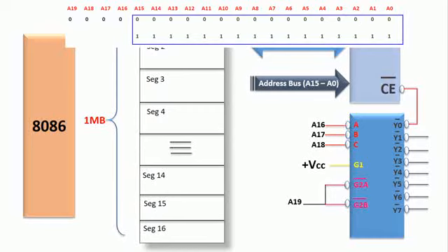Throughout the combinations, from the minimum to the maximum, these 4 bit positions should always be 0, because if the 3 signal statuses are not three zeros, then obviously the Y0 is not going to be selected. If you want to select the Y0, these 3 bit positions should be 0, and in order to get the functionality from the enable, the A19 bit position should be 0. That's why it is always 0. So in the minimum combination it is 0, and in the maximum combination it is also 0.